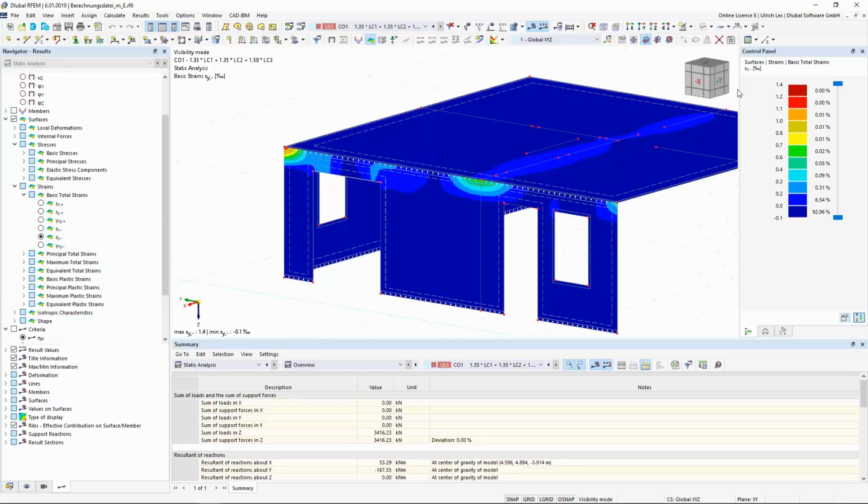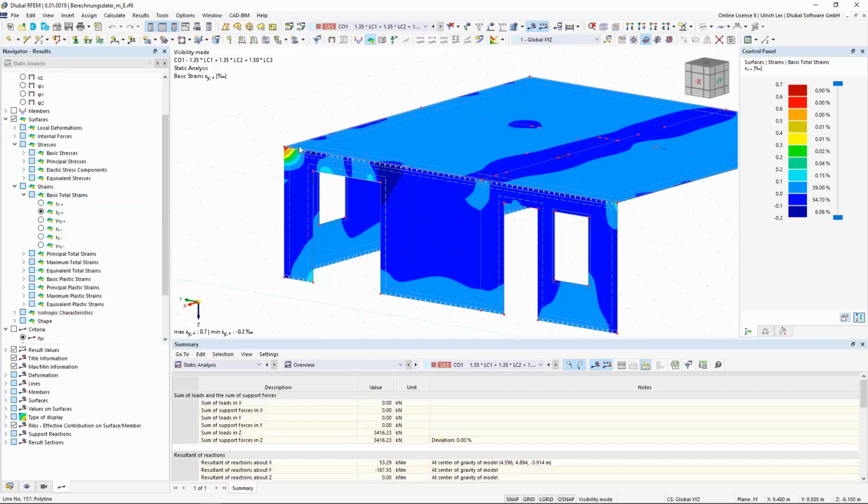That means maybe there is a crack in the masonry. In the beginning, I checked the plus and minus side, and when we remember, the plus side is inside the building and the minus side is outside. Now I can take a look at the inside strains and see there is also a tensile strain. That means my crack will be across the whole thickness.